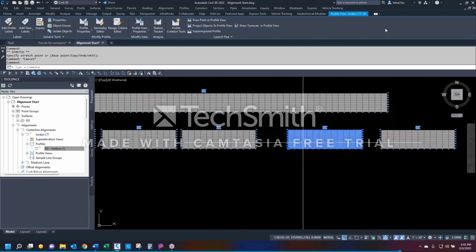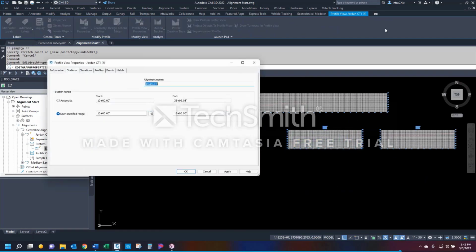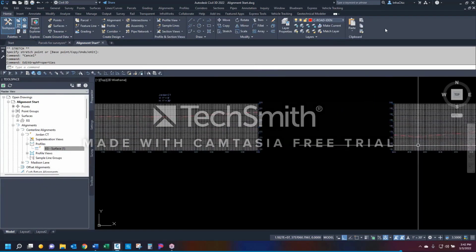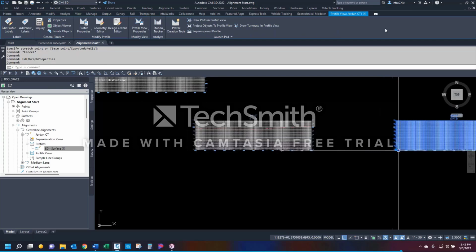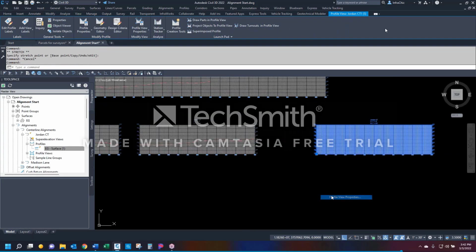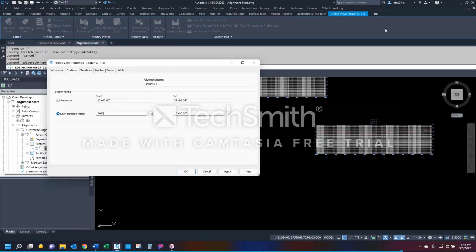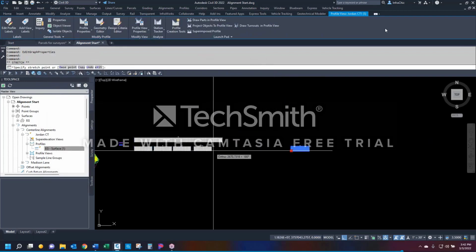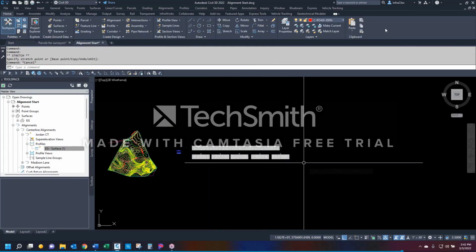Okay. Next one, select the grid, right-click, profile. See how this is routine now. 28. And 6 and 8 is 34. Yeah. Routine, and yeah, that's right. 34 puts it way over here. And grab and drag it back. And then the last one is 34 to the end. 3,400 to 4,000. Now, I have grids everywhere. Beautiful. Looks great, right? Okay.